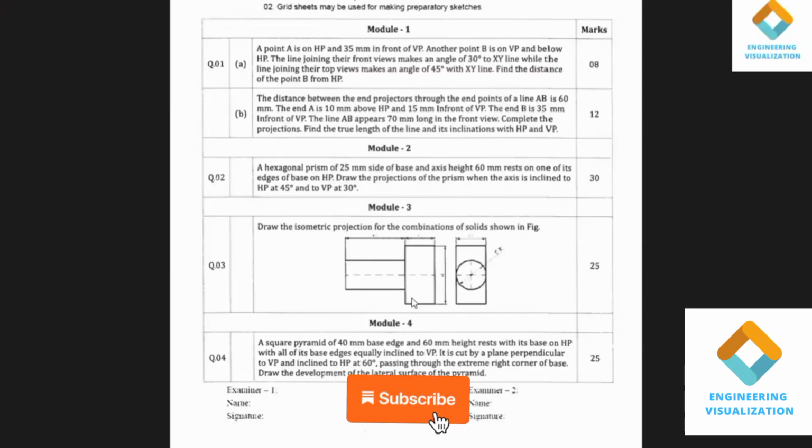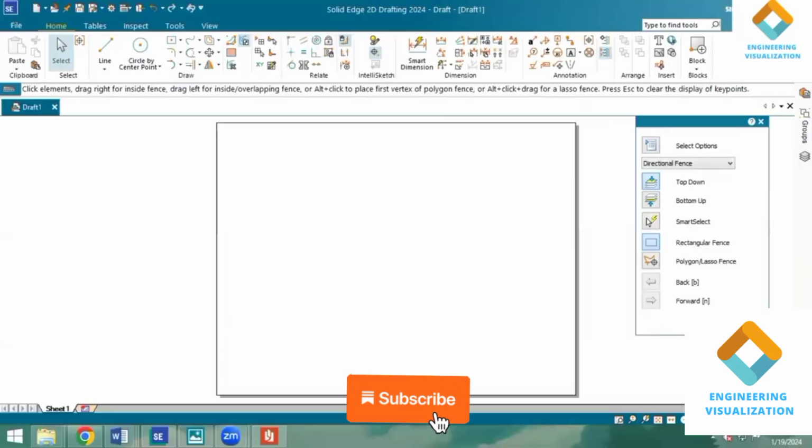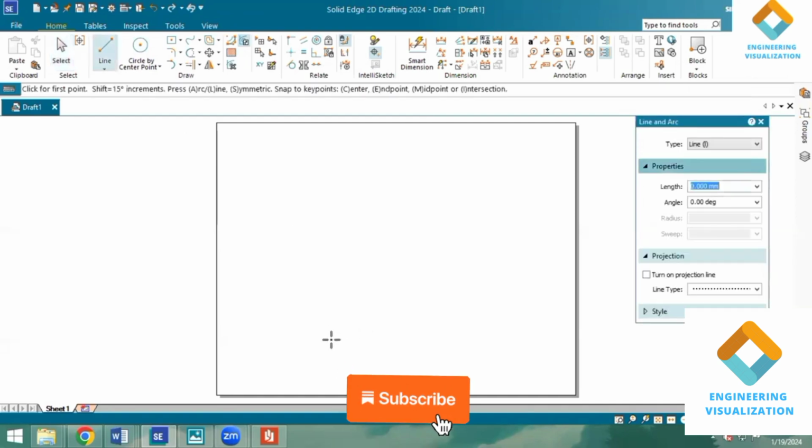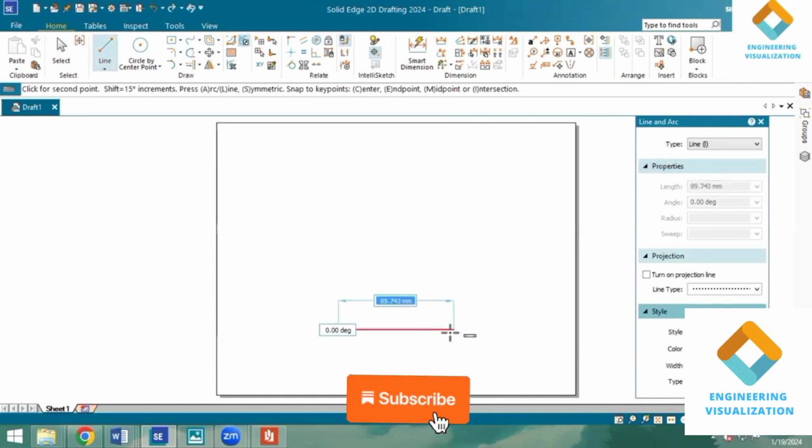Combination of cylinder and rectangular block. Okay, so to construct here, first we need to take one horizontal line as a reference. From this reference point, I'll draw one line, that is a line with an angle of 30 degree. So here I'll take 60 mm. Okay, and angle will take 30 degree because in isometric we should use angle 30 degree.